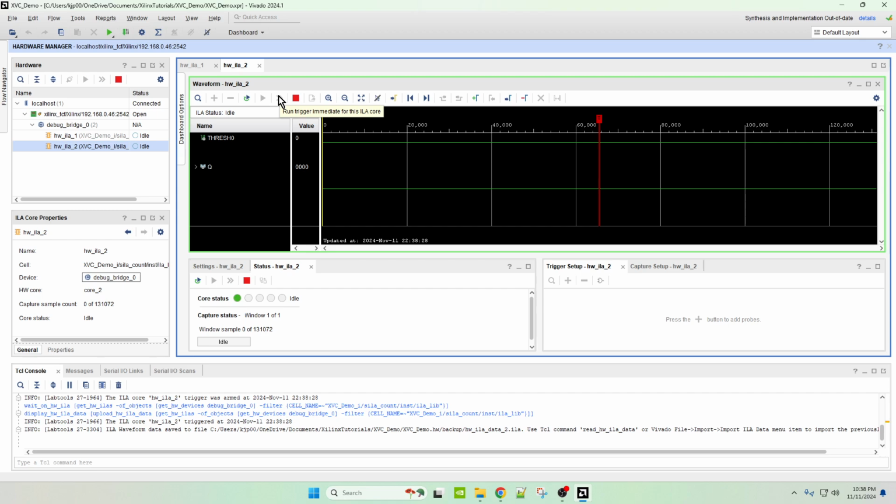The only caveat on using this is the JTAG frequency. The only JTAG frequency that this works at is 10 megahertz. The default is 40 megahertz. So it doesn't matter for debugging waveforms and the ILAs like this, but if you were to try to load a larger Linux image directly into memory, do keep in mind that it is 4 times slower than the stock speed. And as far as I'm aware, I don't think there's any way to change that. But that's the only restriction.